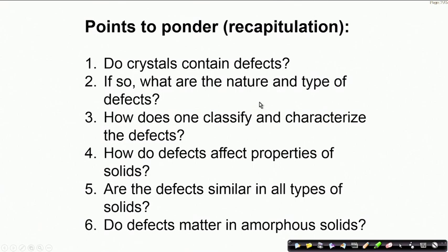So we would now like to wind up and summarize what we discussed. First of all, we realize that crystals, when we describe them from an ideal point of view, give us an impression as if they are all defect free, but in reality all real crystals will carry defects. And one of the reasons I mentioned already is that having a certain density of point defects actually increases the stability of the crystal. Every system in the universe tends to minimize its Gibbs energy, and one way of reducing that for crystalline solids is to have a certain density of defects.